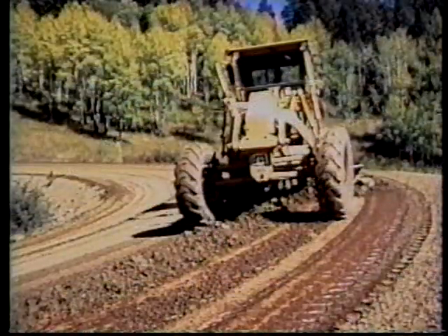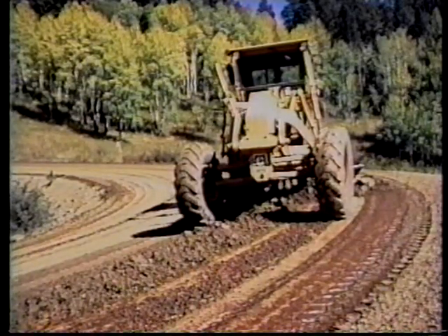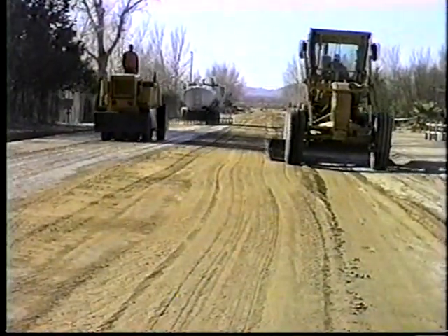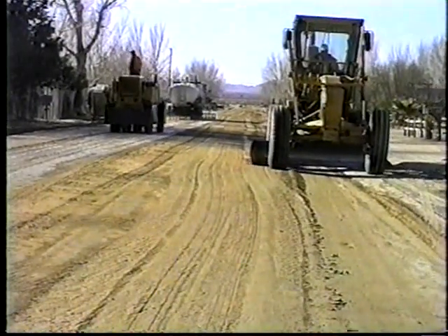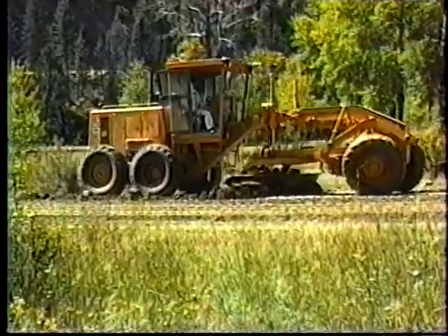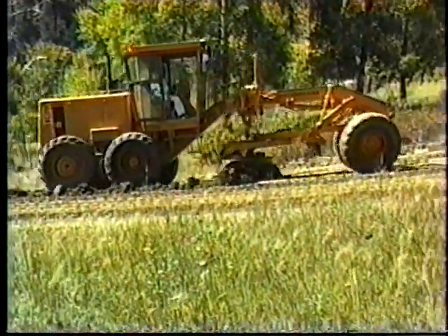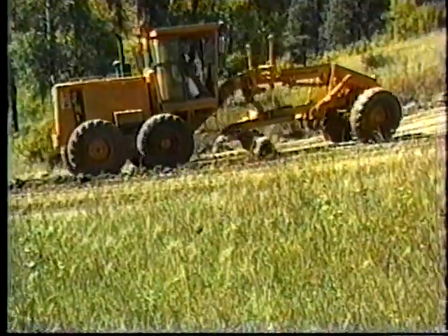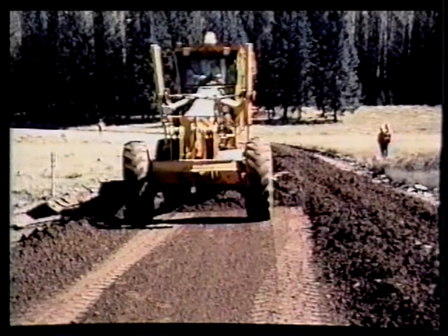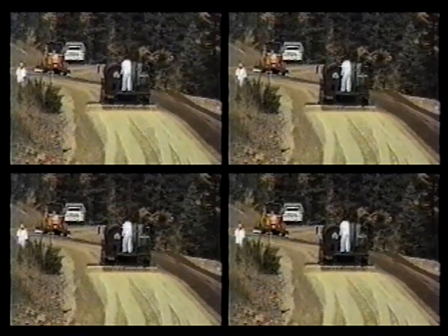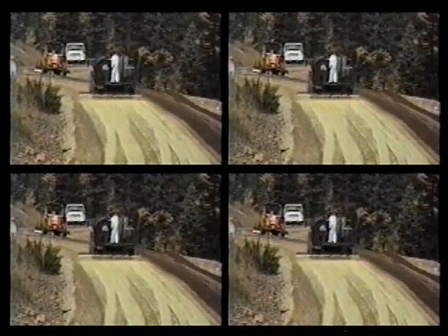In all the applications we are looking at here, roads at a wastewater treatment plant, a Forest Service road, streets through a rural town, among other applications, road oil is being processed with aggregates of varying quality and consistency that are already in place on the roads. When working with marginal materials that don't meet strict gradation standards, or aggregates which have been degraded under use on the road, the neutral chemistry or non-ionic formulation of road oil resin-modified emulsion is a real plus. These situations require an emulsion with maximum workability and excellent coating characteristics in order to provide effective bonding.